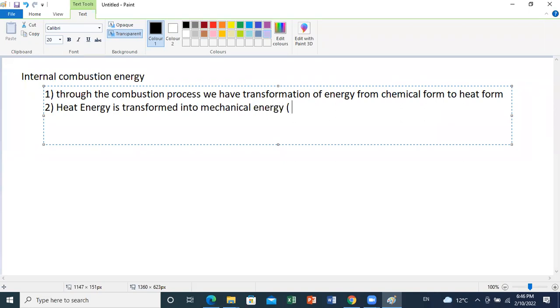It will do translation. I will do for you a small picture to illustrate what is happening. So first, we transform this heat into an expulsion energy, a push on the piston, which will give it a translation motion. And this translation, so we'll go from one mechanical energy form to another. We have translation transformed into rotation of the crankshaft.